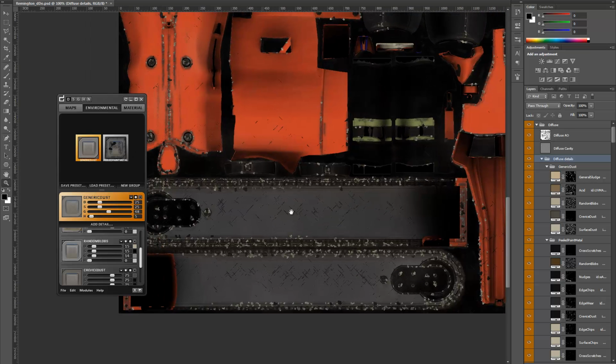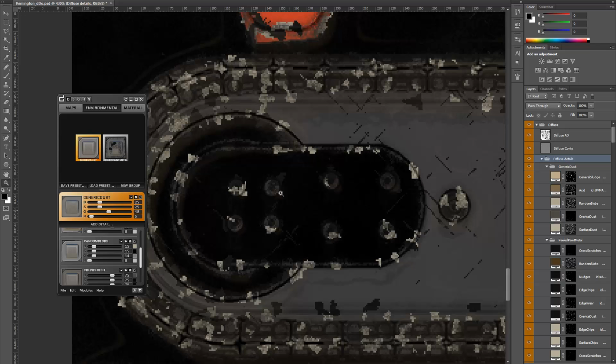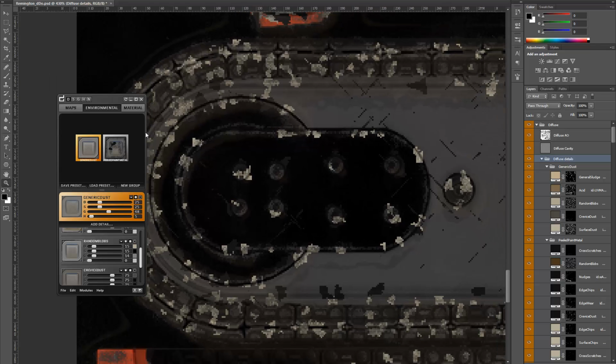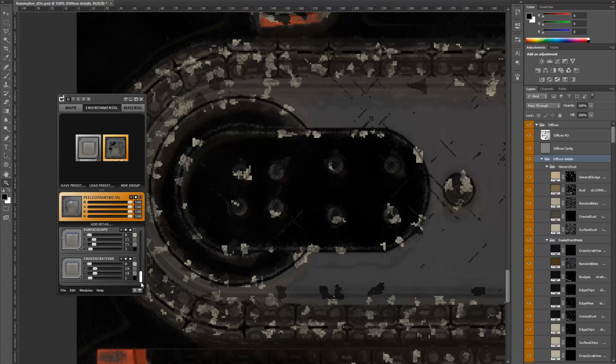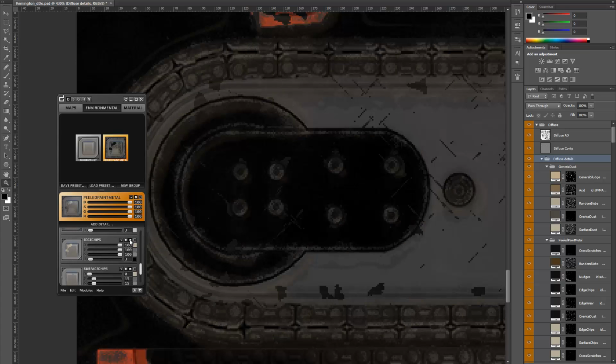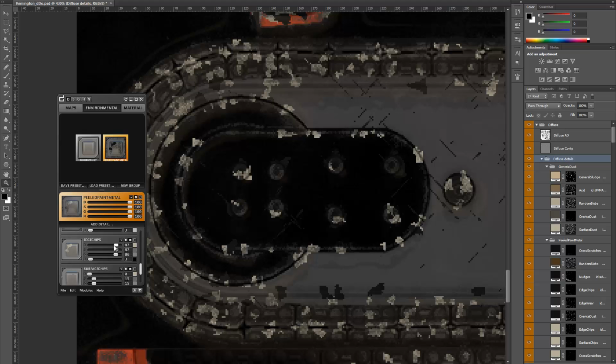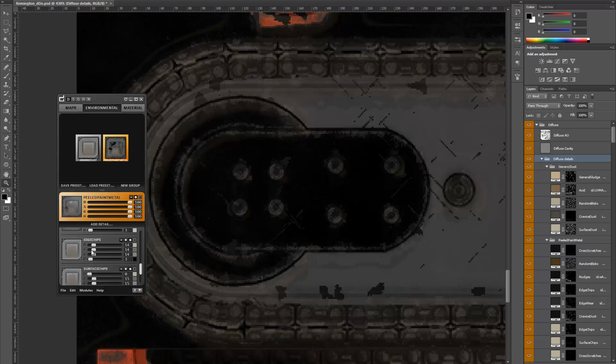And now I'm seeing that we have some extreme edge wear or edge chips here. So I'm gonna go back into the first group we got from the preset from the automation hub, and toggle on and off the edge chips. I'm noticing that's not the one. I'm gonna see if there's a different one. That one? Yes, perfect. So I'm gonna hold down Shift and drag these down to around 20% or 15%. Like so.